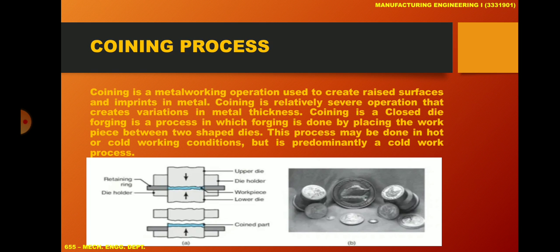The process may be done in hot and cold working conditions, but predominantly cold work is better, because in hot working there will be chances of fins, flash, and oxidation. In cold working there will be neither.